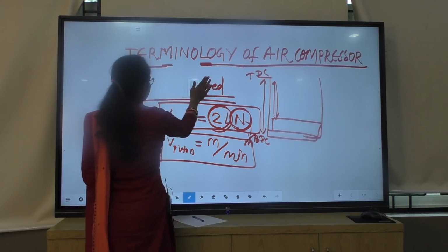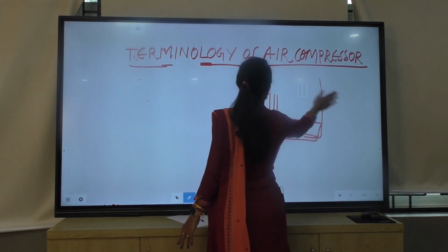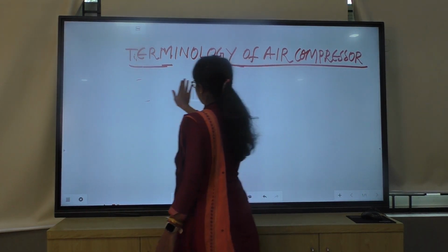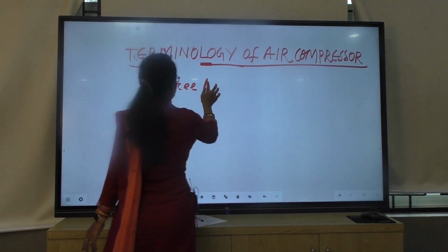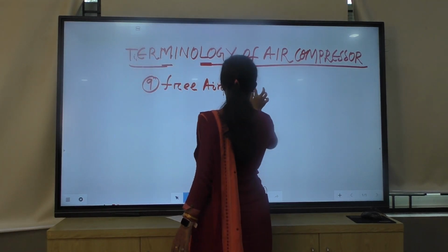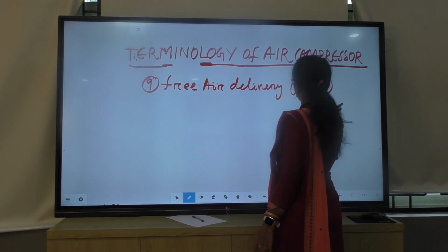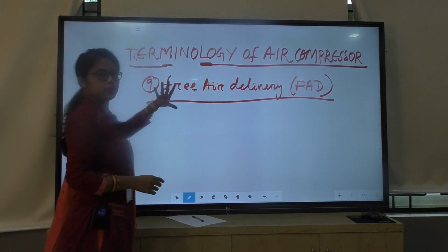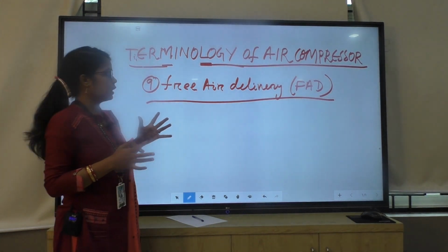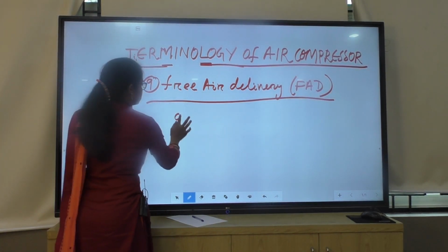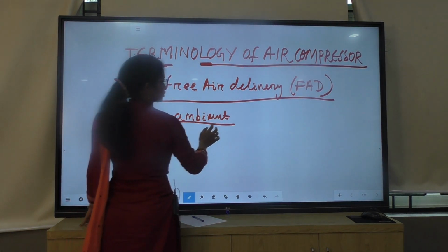Then coming to the next terminology, that is free air delivery, FAD, this is important. Free air delivery. What do you understand by this free air delivery? That means after the compression process, the air corresponding to ambient condition after the compression process, that is called FAD.